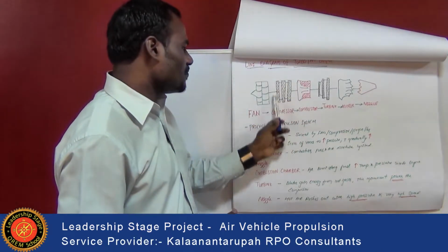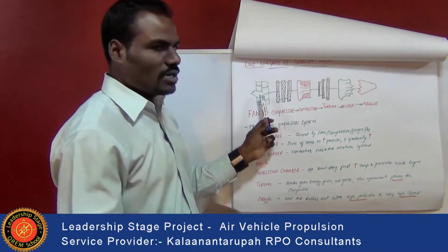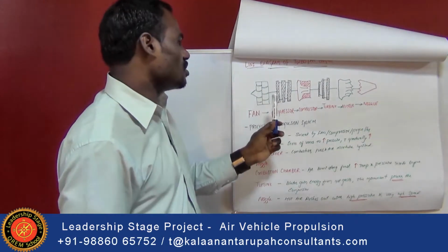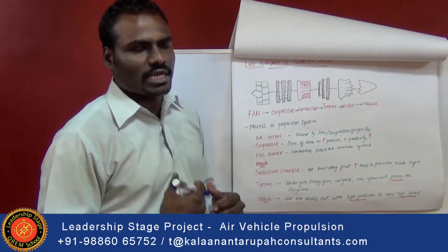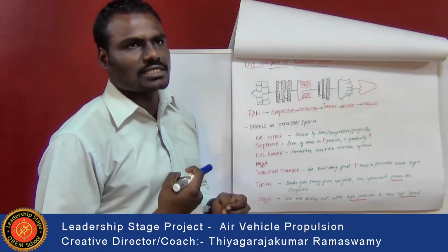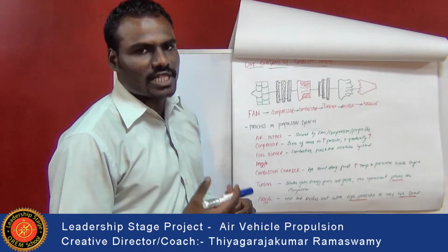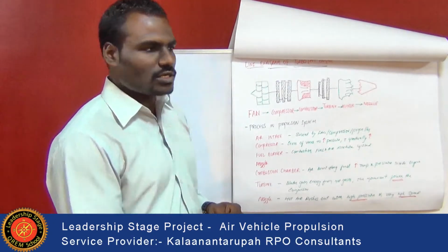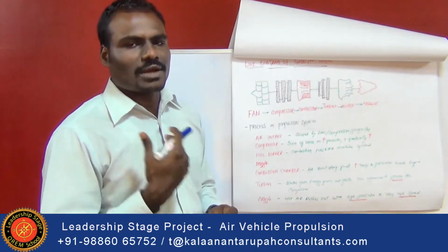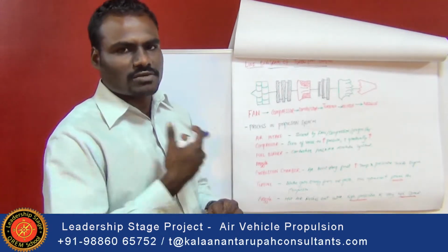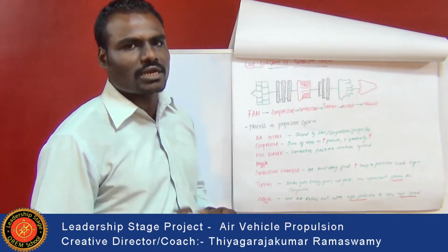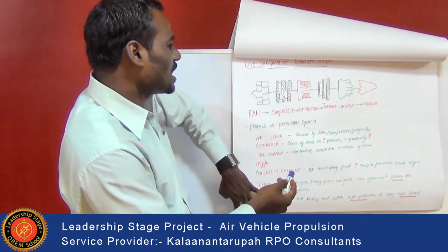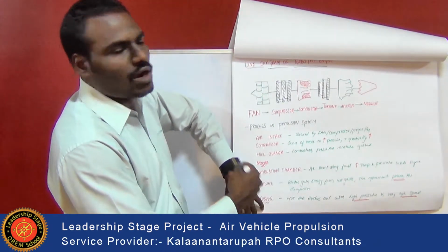After the air is pulled in from the atmosphere, it is subjected to the compressor, where the temperature and the pressure of the inlet air are increased, and it is then sent to the combustion chamber where the combustion process is carried out with respect to the mass flow rate required by the engine to get a better efficiency. This shows how the actual turbofan engine works with respect to its components.